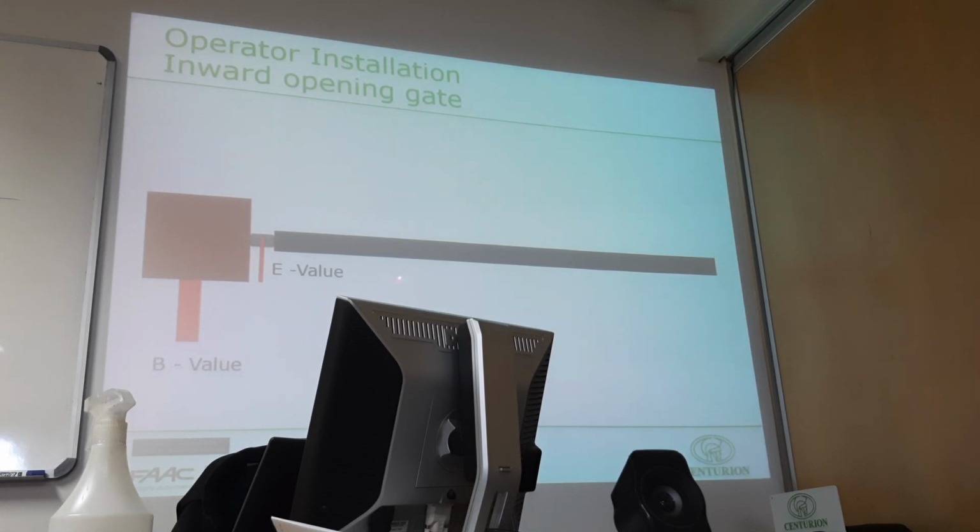This you can't really change unless you tell them, listen here, this pillar is 600, and on the Vantage 500 we can go 245. So if this is center, that means this is 300. This is out of spec. So we can't put a motor on here because this is 300. We can only go up to 245 on 90 degree. If you want 80 degree, then we can have it. Maybe then we can have an E value of 300. But we still don't like it. So maybe we need to start cutting out some of your pillar.